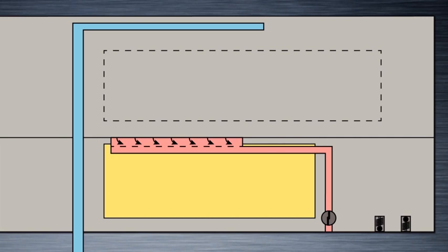On the other hand, a single negative pressure relief valve located aft on the lower left fuselage protects the airplane's structure from being damaged by negative pressure differentials. This is especially important during a rapid descent, such as after a rapid decompression. When pressure outside the aircraft is 1 psi more than the cabin pressure, the negative relief valve opens. Notice that this valve is independent from the 737 NG pressurization system, and it requires no crew action.